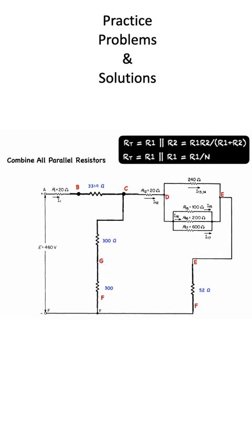In a circuit of three or more unequal resistors in parallel, the total or equivalent resistance, Req, is first found by finding the reciprocal of Req, which is equal to the sum of the reciprocals of the individual resistances.